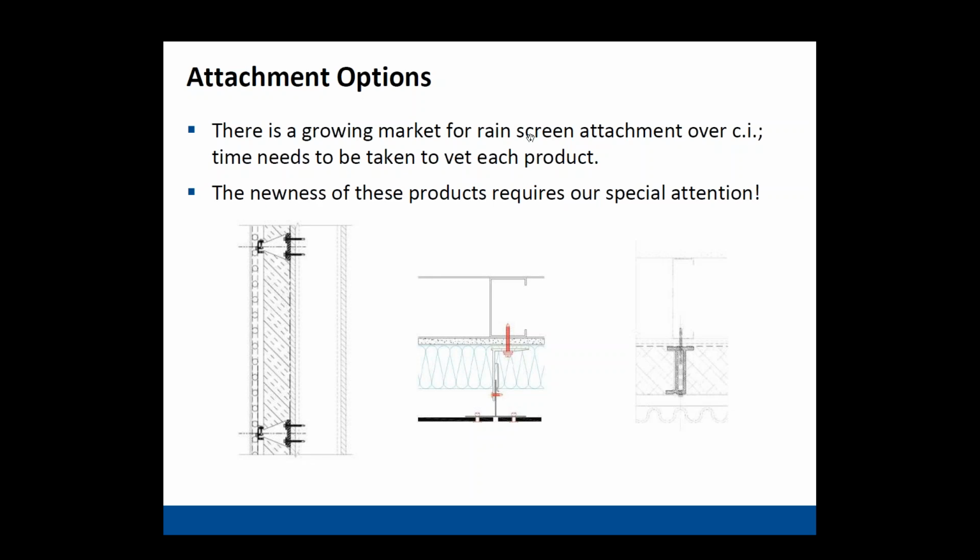Zeke, you want to weigh in on the continuous insulation and the attachments? Sure, yeah. In the Southeast, we're probably the last guys to really get in on the ASHRAE 90.1 and all the different continuous insulation attachment systems, and oftentimes we still aren't seeing outboard insulation in our wall assemblies. But we're learning quickly on it, and Eric's right. If you can come up with the next great gizmo to make this work, you'll do okay in life, because there's a lot of momentum behind this right now, and justifiably so.